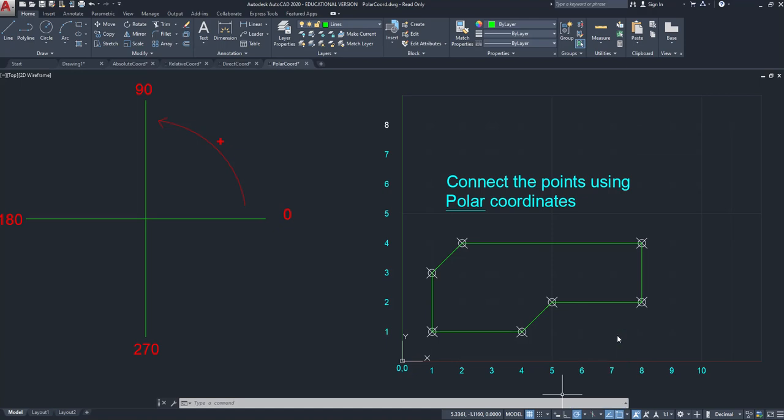So if I click on 45, 90, 135, let me show you what this does. At every 45-degree angle, I get a snap. Do you see that? And if I click, I get a perfect 45-degree angle. 0, 45, 90, 135, 180, 225, okay? If I come down here and click the 10-degree increment, I get 0, 10, 20, 30, 40, 50, 60, 70, 80, 90. You guys get the idea, okay?